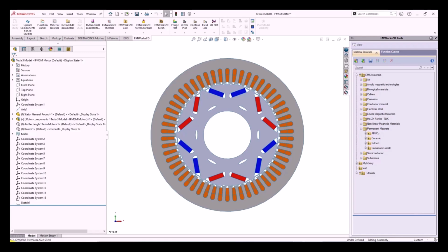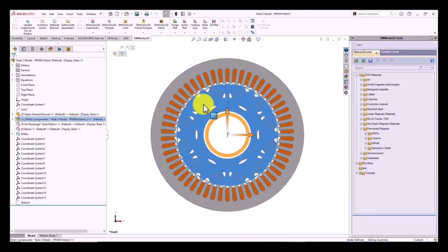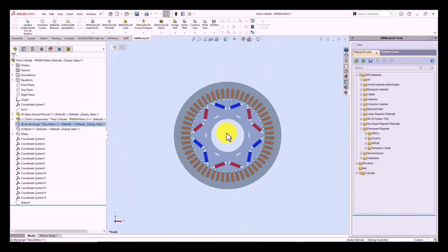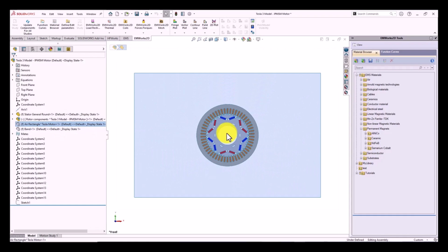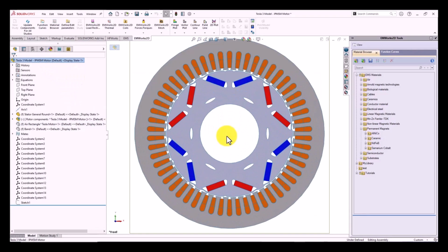Our CAD model is the motor assembly with all its parts. These parts include the coils, the stator core, the permanent magnets, and the rotor. Note that we have two additional air parts, one for the air surrounding the motor directly and another outer air component. Once the study is created, the first step in analyzing an assembly in CAD software is to specify the material types of all bodies.